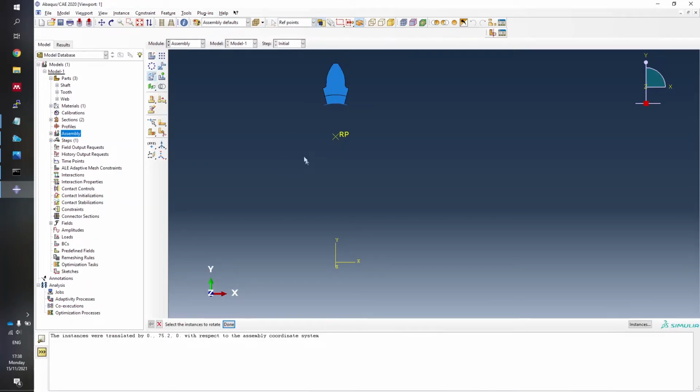We'll now press rotate, and we will select these instances to rotate, but we will choose the center of rotation to be that reference point there. Then we'll rotate them by negative, because I'm going to do a clockwise rotation, 157.6 degrees. This is the transform that you can calculate based on where you want your initial tooth positions to be. And we'll select away from that.